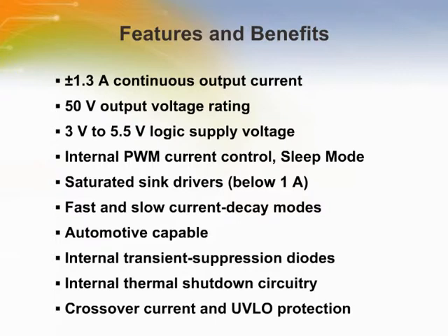The peak load current limit is set by the user selection of an input reference voltage and external sensing resistor. The fixed-off time pulse duration is set by a user-selected external RC timing network.